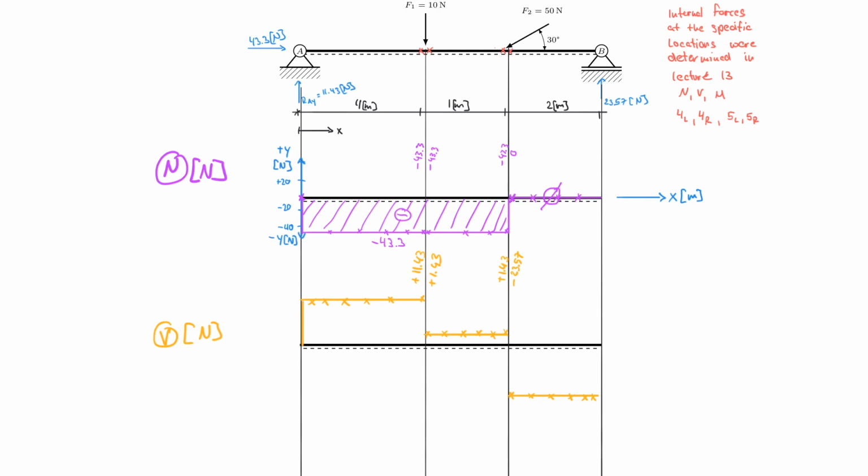Okay, and then if I reach the next instance where I have a jump in the force, I have to, of course, go down, and I do the same thing here. And then, similar to my logic that I used right here, I have to end up at 0 here as well. So I cannot keep this open here, because the value has to go back to 0. And if you don't believe that right now, you will definitely believe that if you have some practice with these problems. But now it's a closed diagram, or a closed shear force diagram, which I complete now by my plus